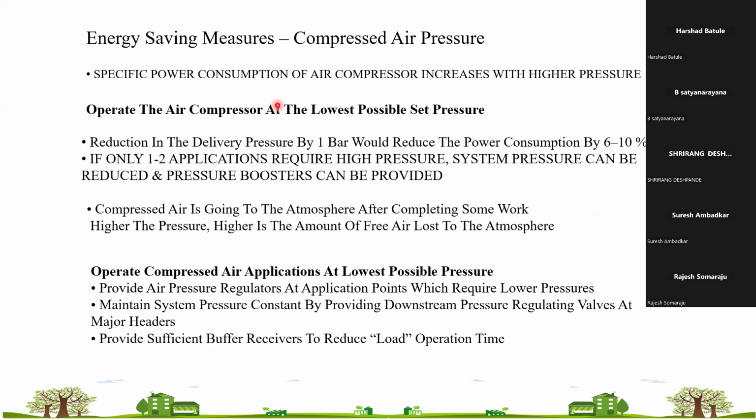So a pressure drop will be there, because you are creating a barrier for air to pass, so more work has to be done to suck that air. So those filters need to be regularly maintained, or a dust-free environment has to be there.